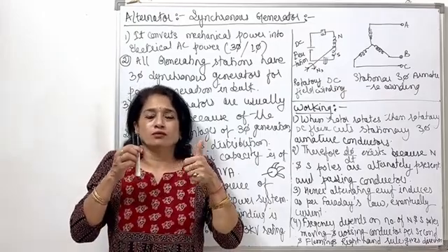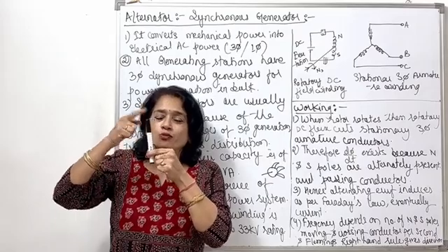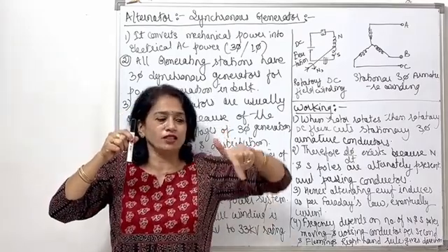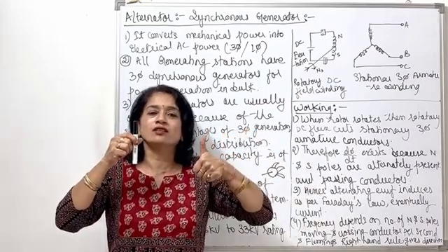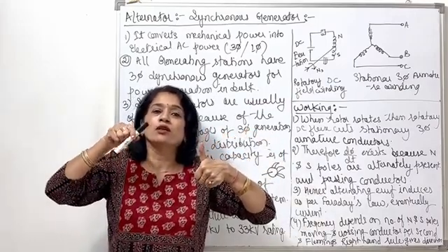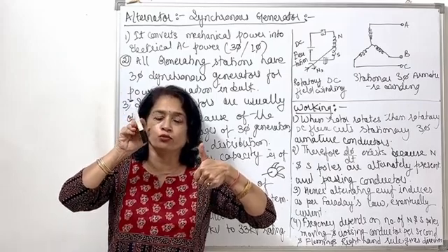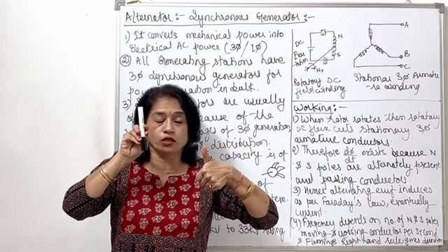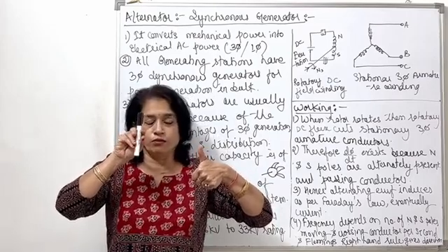With respect to this electrical representation, I can explain that suppose the north pole is here, the south pole is here, and we are turning it. So here I have A phase, here I have B phase, and the C phase is like that. These conductors are subjected to the variation of flux because of the rotation of the rotor, because of the rotation of the field winding, which is producing the DC flux.